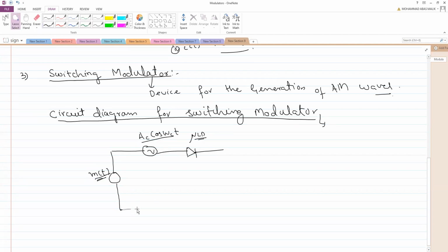Yes, sir. Okay. Linear and nonlinear device, how can you conclude? You can conclude this from the superposition principle and homogeneity principle. If it does not follow the homogeneity and superposition principle, then you can say this is a nonlinear device. That means current will not pass in both directions. The current will pass only from P to N. It will not pass from N to P. Of this, there will be some current in microamperes, and that will be pretty negligible. You can neglect that. That means in reverse bias, whenever you reverse bias the diode, there will be no current. But in case of forward biasing, current will flow. In the ideal case, you can see this will act as a short circuit in forward biasing, and as an open circuit in reverse biasing. So that is what you have to remember here.